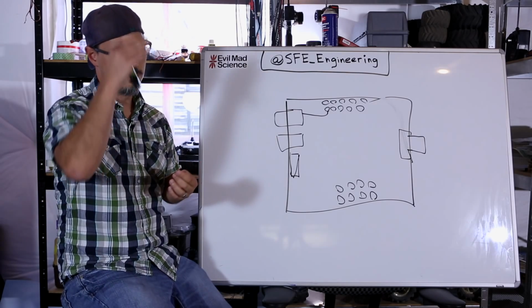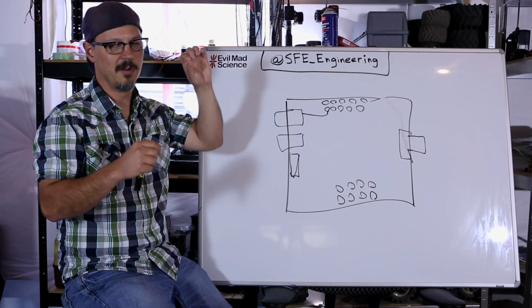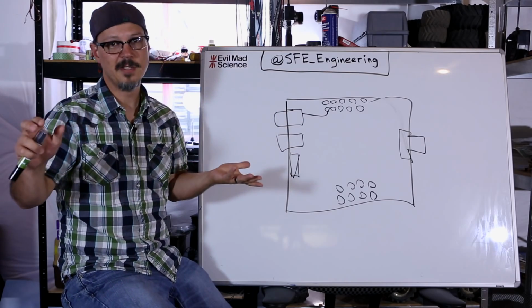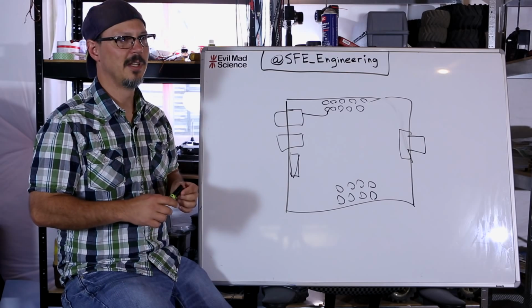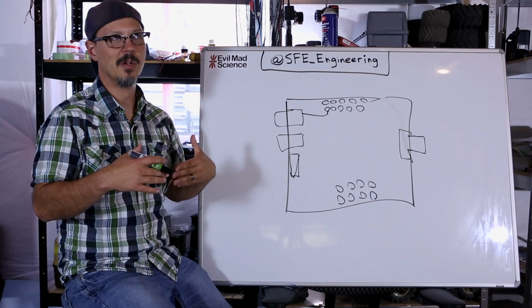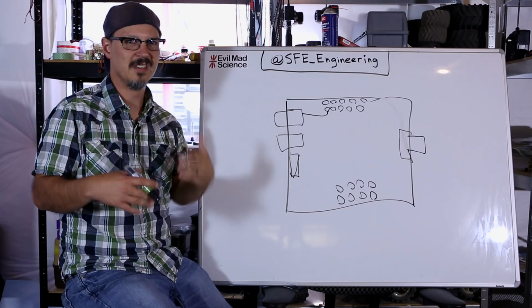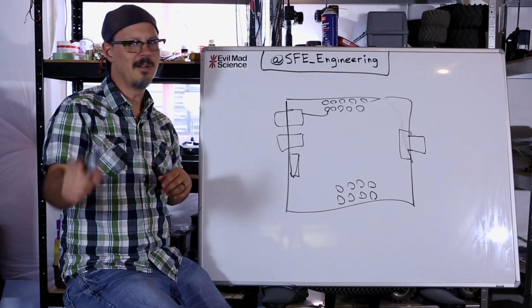Circuitcalculator.com. You can put in a current that you're going to run and how heavy your copper is, and it'll tell you how big your trace has to be. And generally, a 10 mil trace is good to about 30 milliamps before it starts to become resistive and a problem.